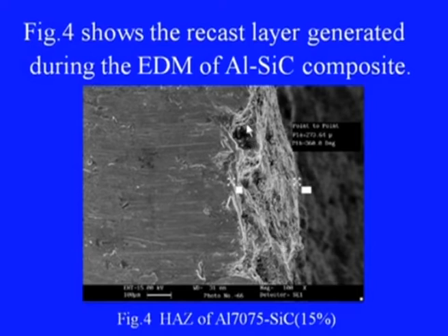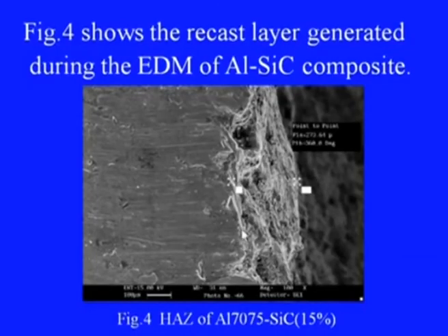and there are certain flaws, porosities, or in some cases cracks, like the micro cracks we can see here on the screen itself. Those are also present in this layer. Therefore, once this machined workpiece is put into service, there is a possibility that the part may fail through this zone, which is not acceptable. In general, if the part is going for a critical use, then this white layer needs to be machined out or removed by using some secondary processes.